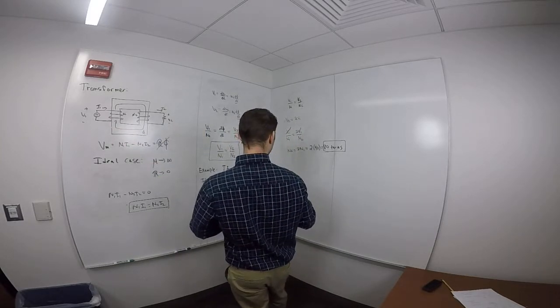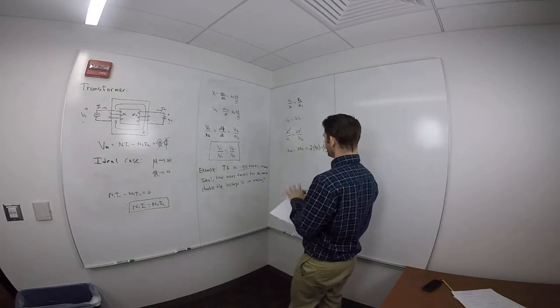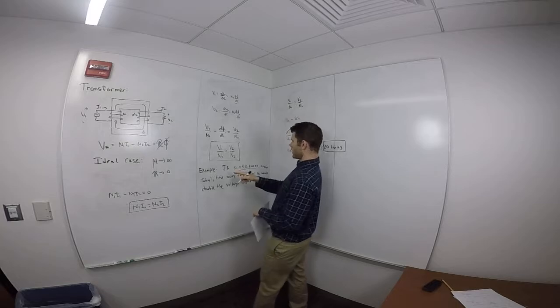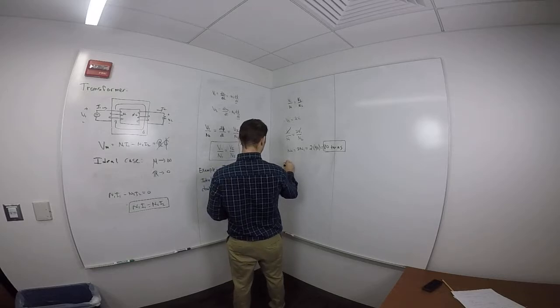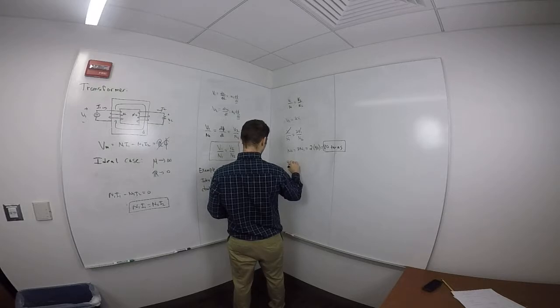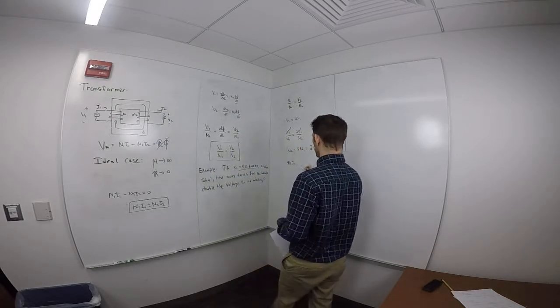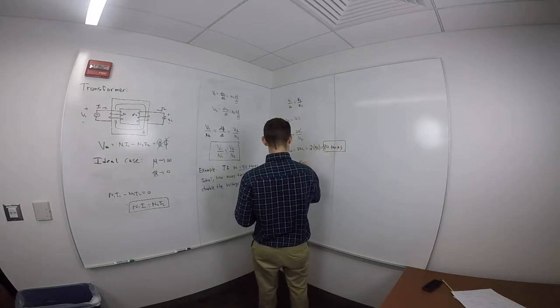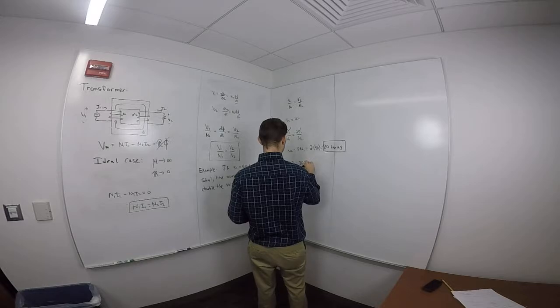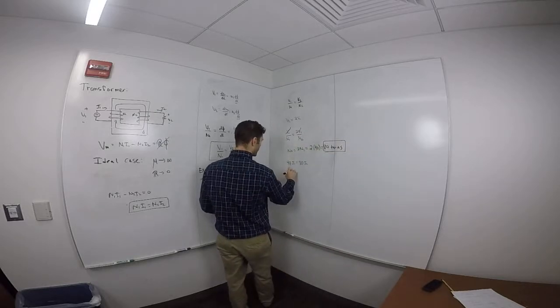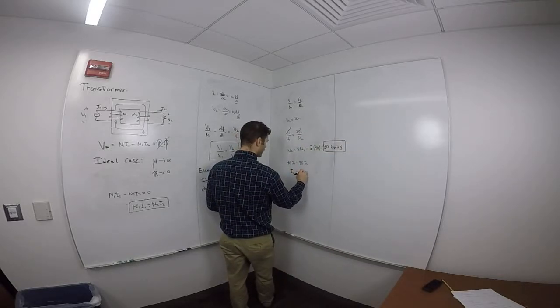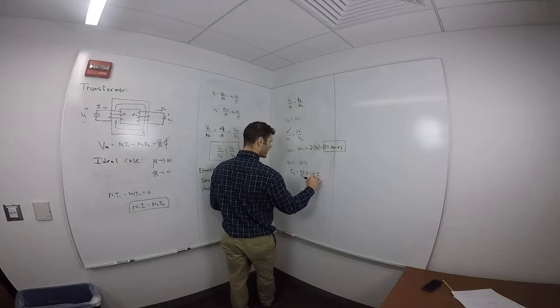And let's check, would that really happen? Well, if we look at this current equation, which is this guy right here, we would say N1 is equal to 40, right, times I1, okay? And then N2 is equal to 80, so 80 I2. So could we get I2 as a function of I1? We would say, well, I2 is going to be equal to 40 divided by 80 times I1, or 1/2 I1, right?